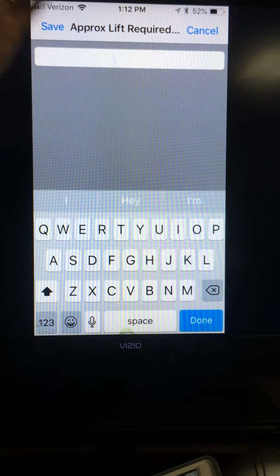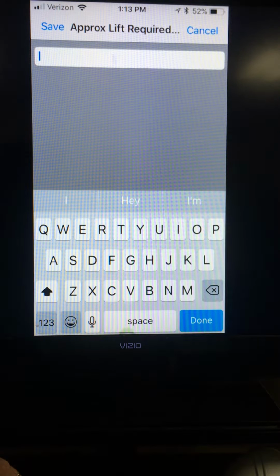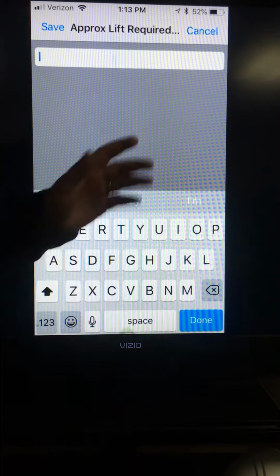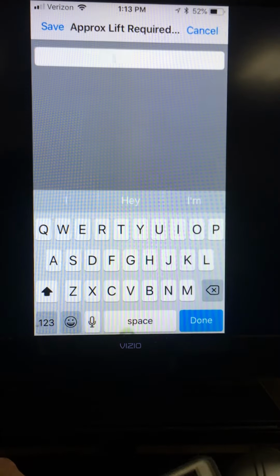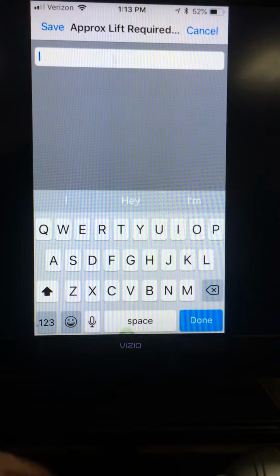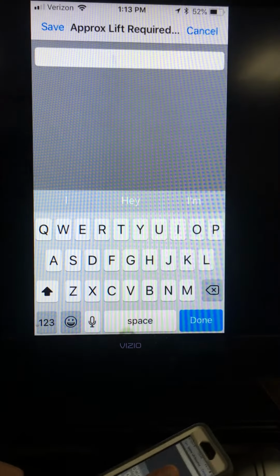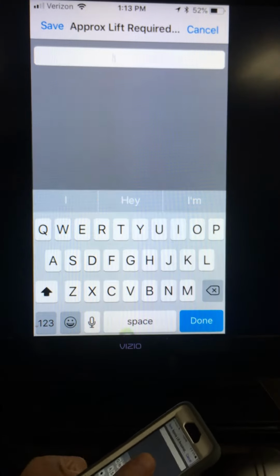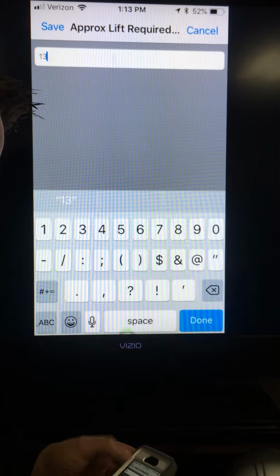Another thing with span, when you determine span and runway length, just remember most brackets are on a 5-foot span. So if you've got festoon brackets, you can count by fives on how many brackets are up there. Same with the runway. Conductor bar brackets are on 5-foot centers, so you can multiply that way. Or you can find out how long your bay is. I know a couple of you guys in our group have some laser tapes. You can measure the width of the bay. You can do this stuff pretty quickly with one of those, and some of those laser tapes are really inexpensive. So approximate lift back there, I'm going to say 13 feet. That's pretty close.